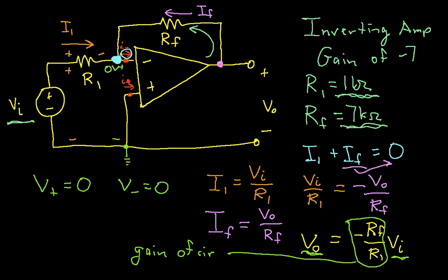So you size R1, and from that RF, taking into account current and power consumption and so on. For a typical op-amp application, R1 of 1 k ohm is a pretty good first guess, typically. But again, you'd want to make sure that you've got it right.